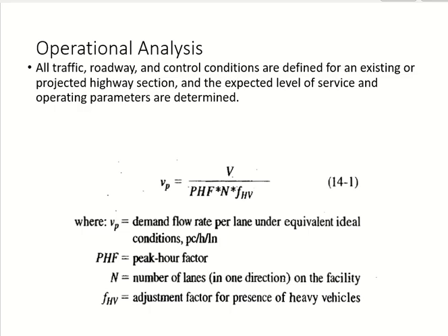That will be counted when you are doing the analysis for the intersection. You are not doing it for the intersection, you are doing it for the segment. For the segment, the lanes added for the intersection, even if they are added earlier, we don't count them. The lane must be in the entire segment.